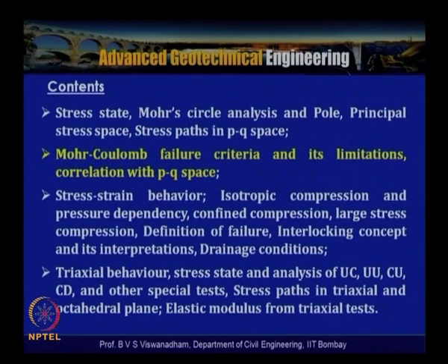Coulomb criterion, and we will discuss how, by knowing the state of the stress on the element, we can determine the stresses at failure, particularly the shear stress and normal stress along the failure plane. So, these are the contents which are given. What we are going to concentrate on in this lecture is the Mohr Coulomb failure criteria and its limitations.